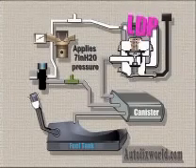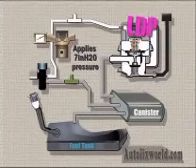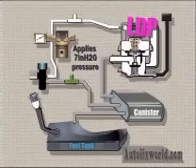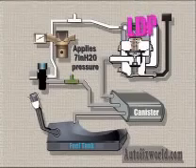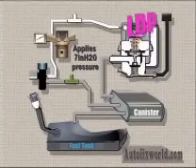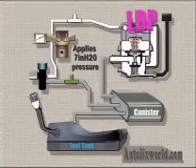This is a very small pressure, equal to about 1/4 pound per square inch. The length of time the pump runs to reach the test pressure and the frequency of pump cycling are both counted by the onboard monitor. For example, if the pump runs a long time to build up test pressure and then comes on again frequently to maintain that pressure, a leak is detected and a fault is recorded.